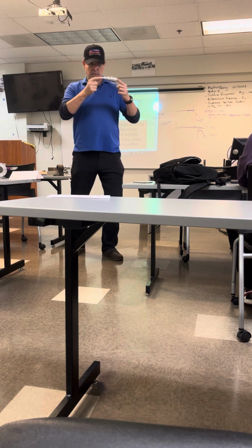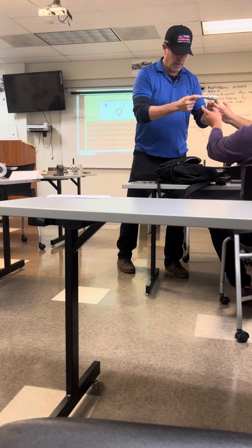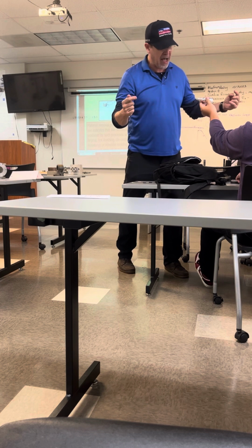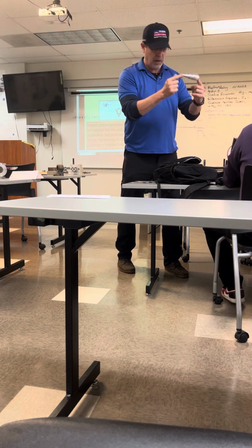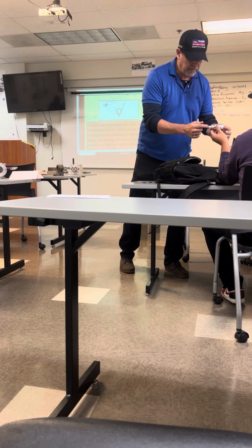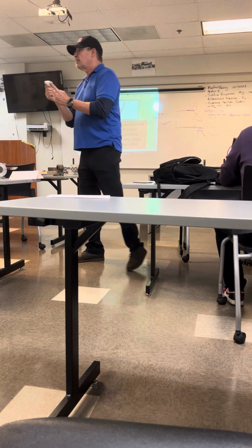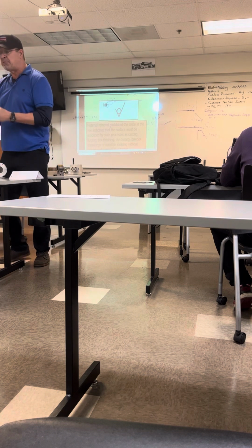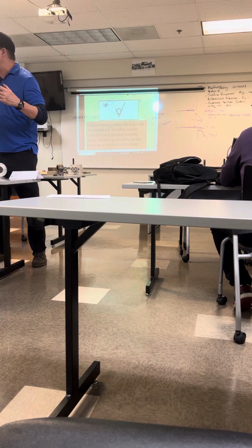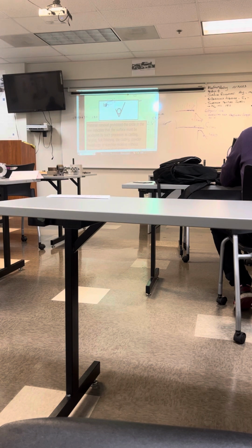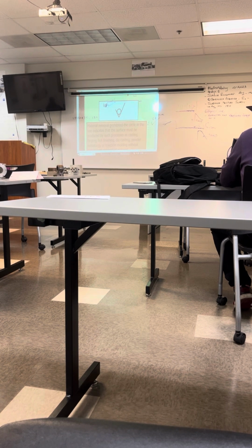When the part is held, you grab it, put it back. Every time you take the part out and put it on again, I will locate the same center. Do you understand what I mean? When the part is located between centers, you hold the center of the part. So that's why many parts, even though you don't see it, have technological holes at the end. Those technological holes allow you to do the part in the lathe and then in the grinder, and the surfaces will be exactly concentric. Does that make sense? That's a technological process.